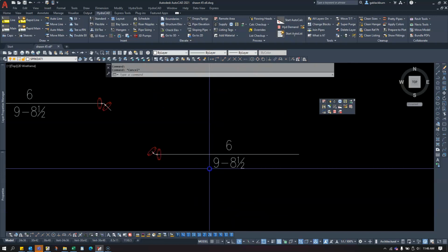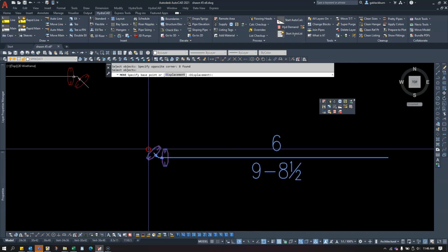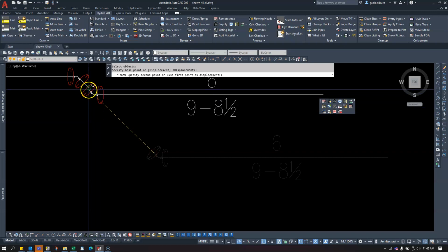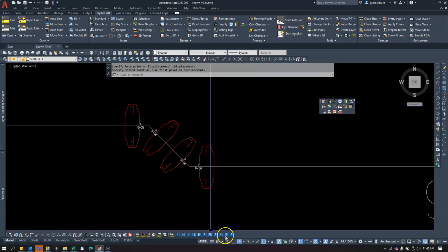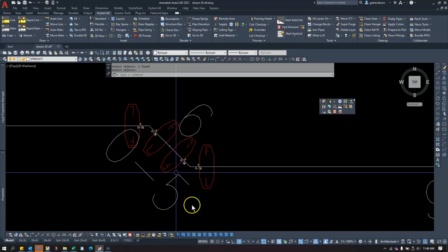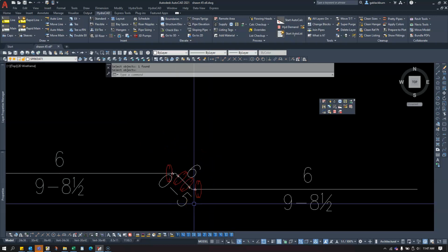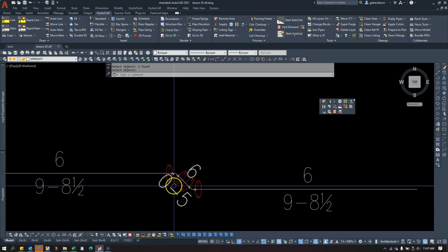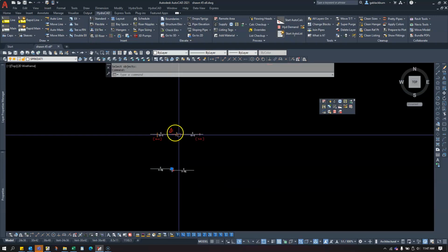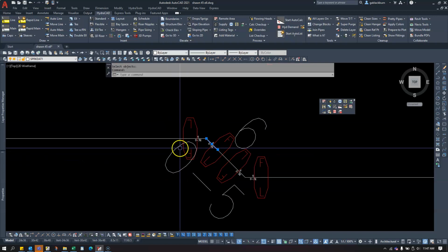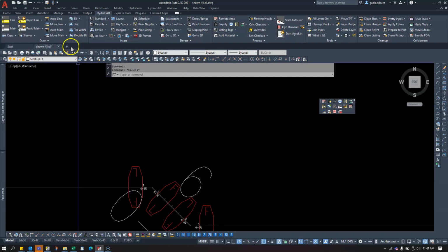From this endpoint to this endpoint right there. Okay, good. So now I have my pipe. I will size it just because, and you can see that we have our 5-inch spool piece in here. Now what's important is we have to readjust this length when we break it in up here. I'll show you what we're going to do and how to get that value.